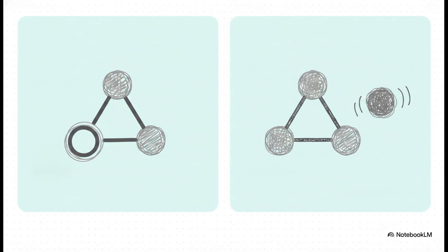On one side, we have P-type silicon. By introducing boron, which only has 3 valence electrons, we intentionally create a lattice with missing bonds or positive holes. On the flip side, we have N-type silicon. Here, we dope the silicon with phosphorus, which has 5 valence electrons. 4 of those bond with the silicon, leaving 1 extra unbonded, negatively charged free electron. So now we have one material packed with positive holes and another packed with negative free electrons.